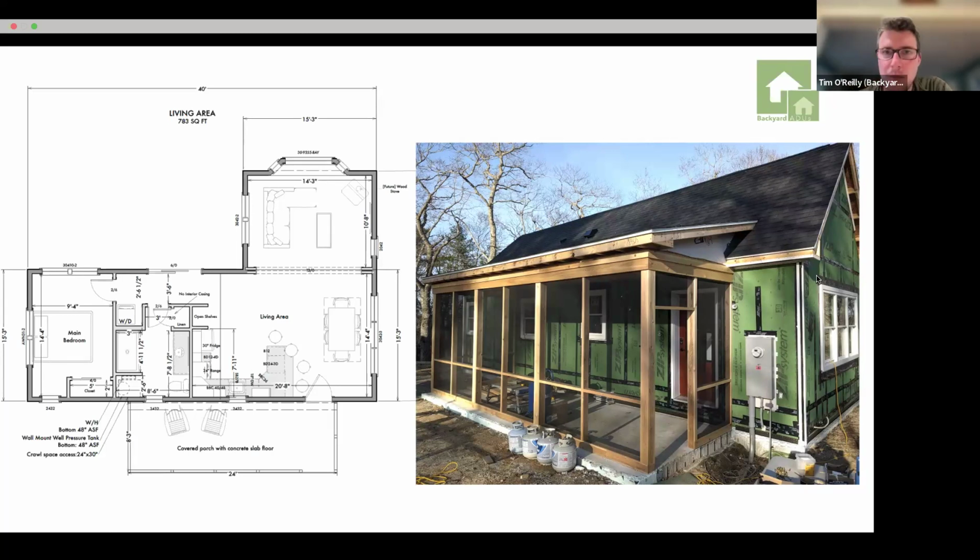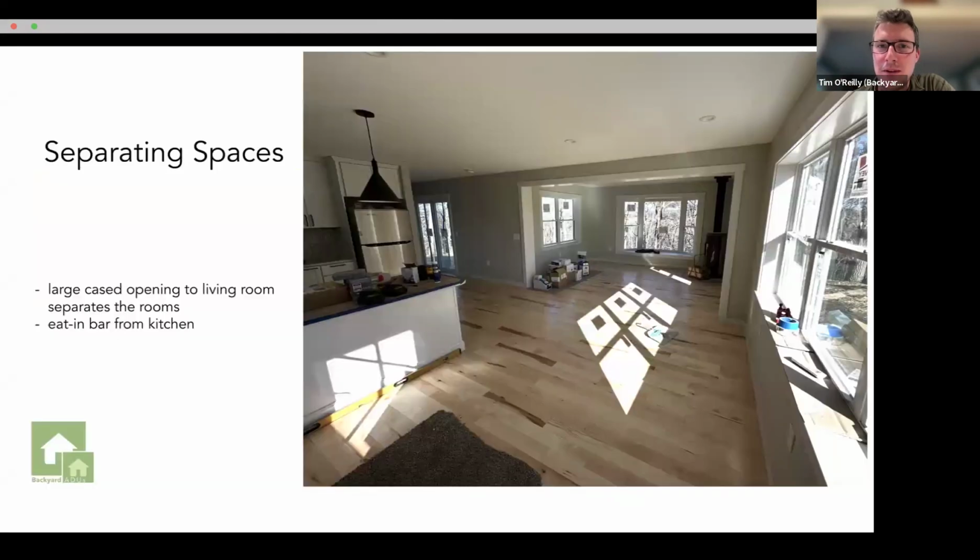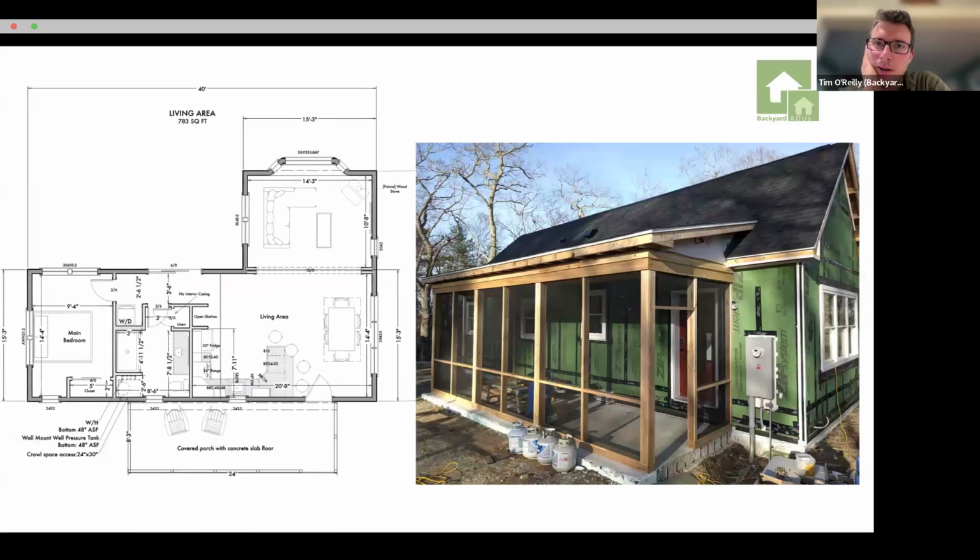If you're doing, what's the photo we looked at earlier? Let's go back. If you're doing a vault, like this house that Jeff highlighted, you may need to change your insulation strategy. You may need to flash and bat and basically have a hot roof where we're in a smaller space, fitting the same amount of R value, our insulation value, to make sure that it's a super cozy and energy efficient home. So a couple different options, but typically this is what we're doing. ZIP R, insulated walls, cellulose, and then our ICF foundation blocks.